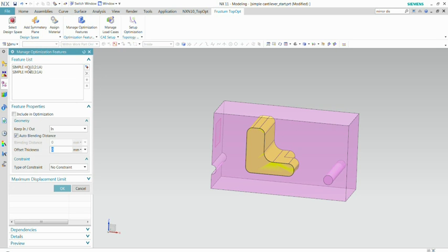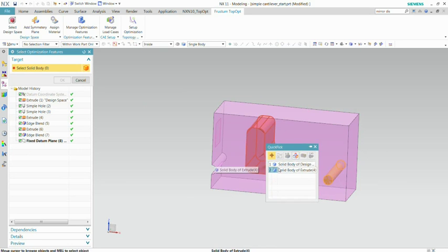Further on, we're going to say that around that central hole that you see highlighted over there on the left, we want at least 1 millimeter of material. For example, we want a full zone for an axis. And at that location the part is also fixed, so that the part cannot move around that hole. We're also going to define an offset around the right hand hole. And finally, I'm also going to add the shape in the middle, the yellow one.